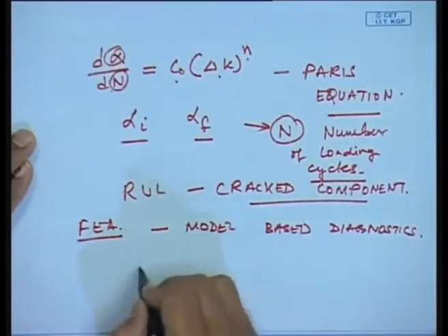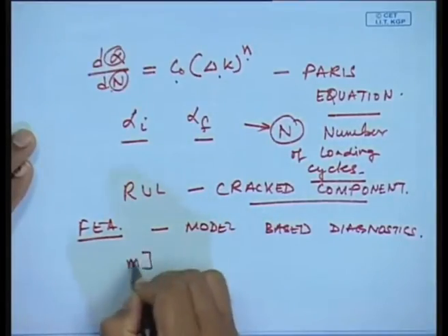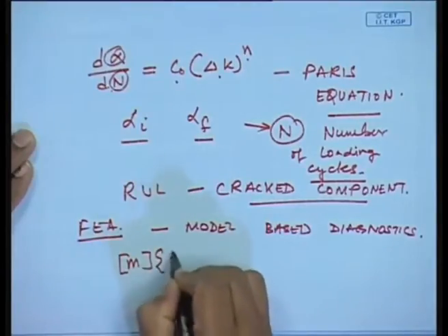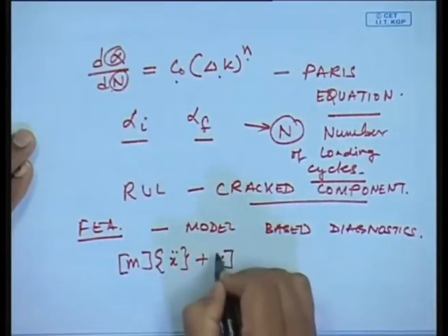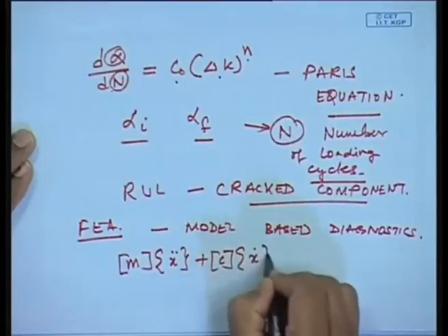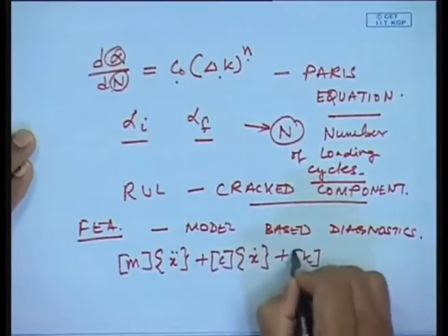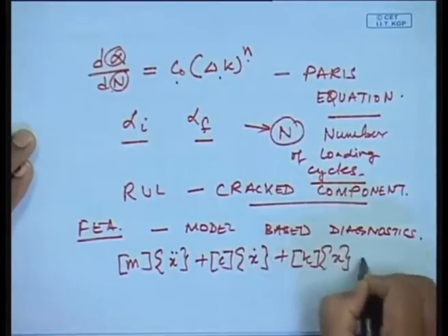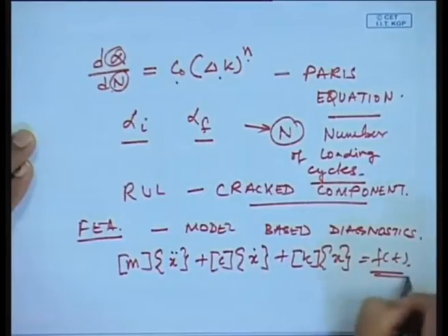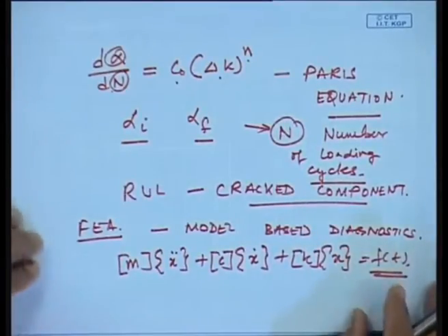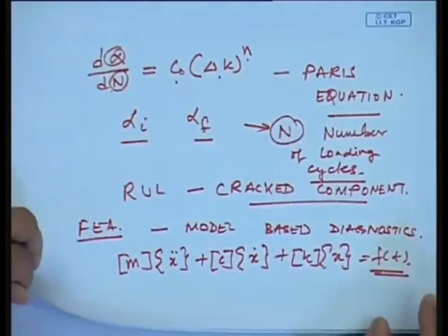What we can do, if you go back to that same equation I was talking about, is that a simple FEA model of the system can be developed and this force can be estimated, and then the model based fault diagnostic procedure or strategy can be developed for the fault detection.